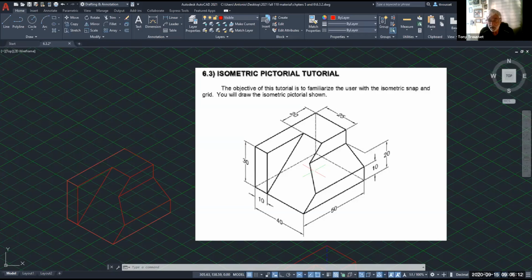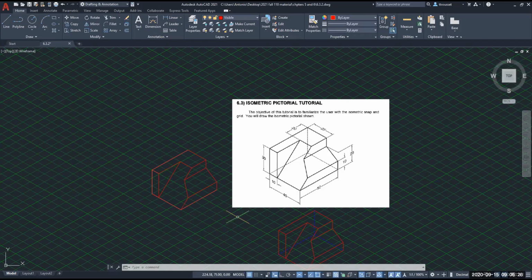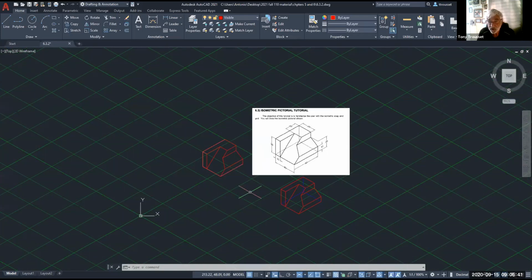So when you say go wild, do you mean don't hover your mouse off in space somewhere, and instead of typing in a dimension, you just type in the angle? Correct. And then you just trim it after. Correct. Because I don't know this distance. I don't know what this distance is, but I know this and I know this. So I could create that square and then trim it. And that gives me that corner, and I could come back and measure that distance. And see, that's where you use the computer to give you answers.